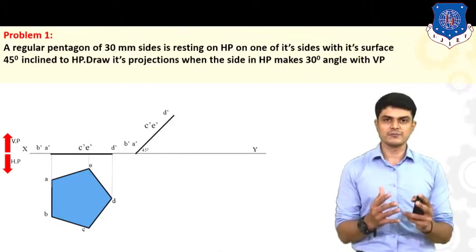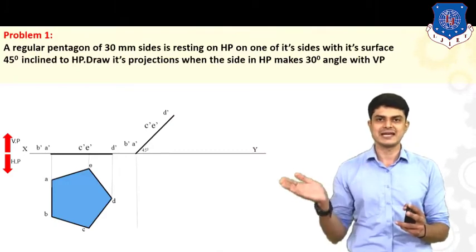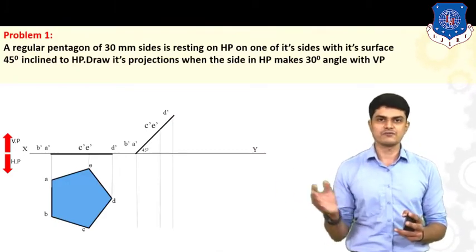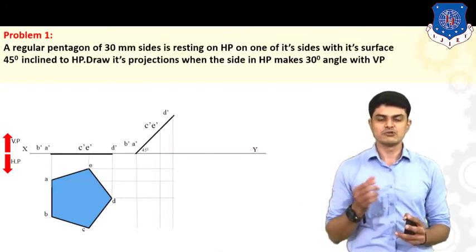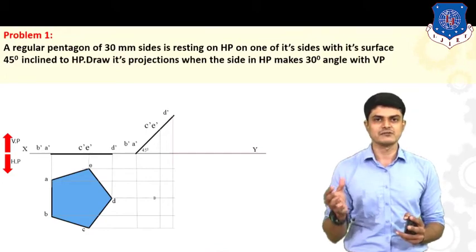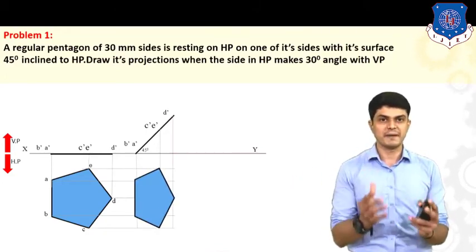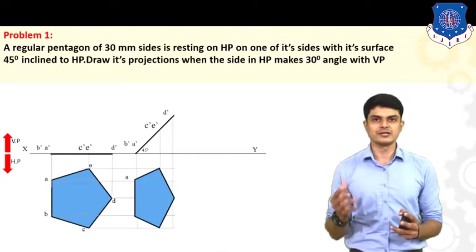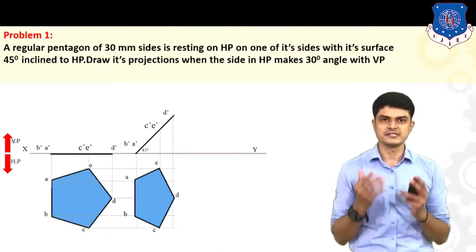After getting all of the points on your inclined line, you must draw vertical lines from each and every point like this, and horizontal lines from each point of the pentagon on the right hand side. You will have points of intersection, and after connecting these points of intersection, you will have this shape generated, which is nothing but your pentagon. Let us give the notations A, B, C, D, E. It is the same fashion as given in your first stage drawing.